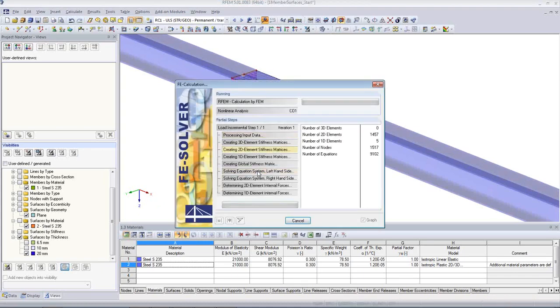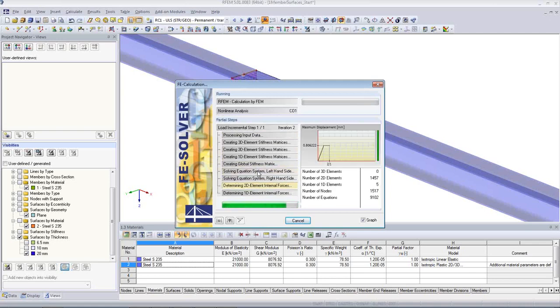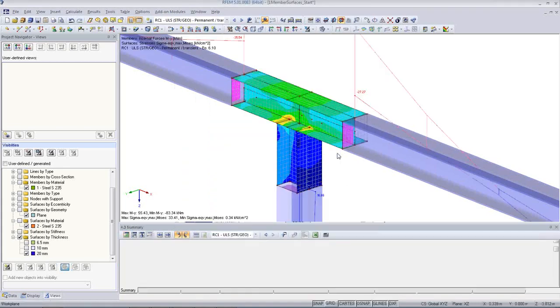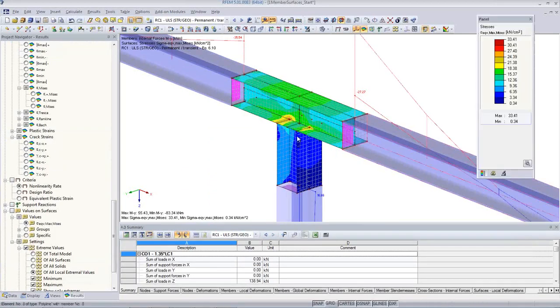Now we do a plastic analysis, so there will be a few more iterations. You can follow the iteration process. You can see how many iterations are here. It's also in a log file, so you can see it in the printout report if you reach the convergence or not, or how many iterations have been done. You can see also a small diagram that shows you, okay, is there some problem? Is it moving away? Is it converging or not? Everything can be recorded and printed afterwards.